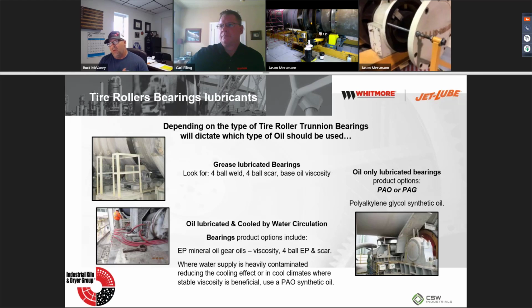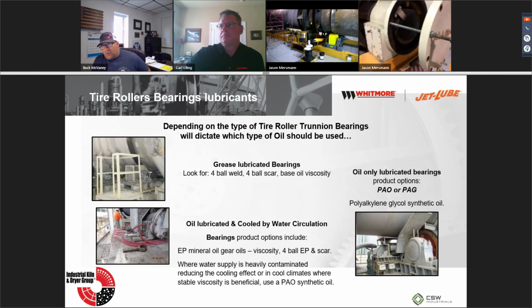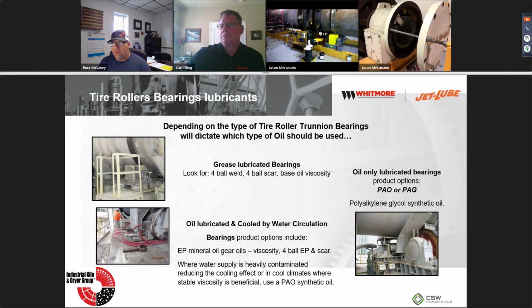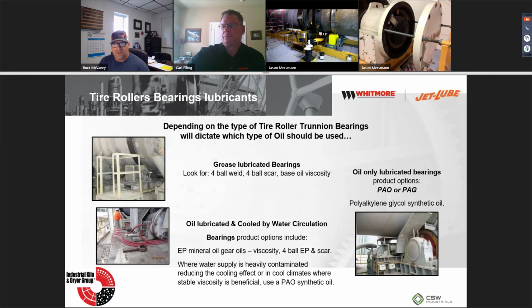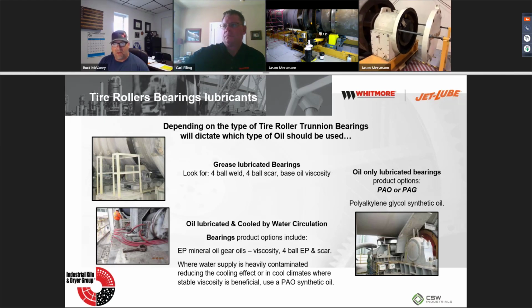Good job, guys. Absolutely. One thing I would add to that, for those of you running water for cooling, and this may go without being said, is always checking your lines. Make it part of your PM program to check for calcium in the line, the buildup that causes restrictions, so you're not getting full circulation through the bearing. Those are things to monitor, especially if your water, like in most places, is recirculated and coming back through, where you see a lot of that buildup.